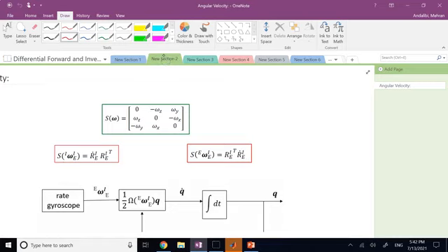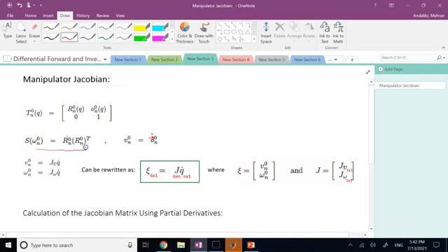So if you go back and look, you see that the skew symmetric of omega of the end effector with respect to I, written in I, instead of E and I we call them N and 0, but that's the same thing, is R dot R transpose, correct? So this equation describes, based on the rotation matrix of the end effector with respect to base, the angular velocity of the end effector, and the time derivative of the origin of the nth frame with respect to the base frame, which is the time derivative of x, y, and z, will define the linear velocity of the end effector.